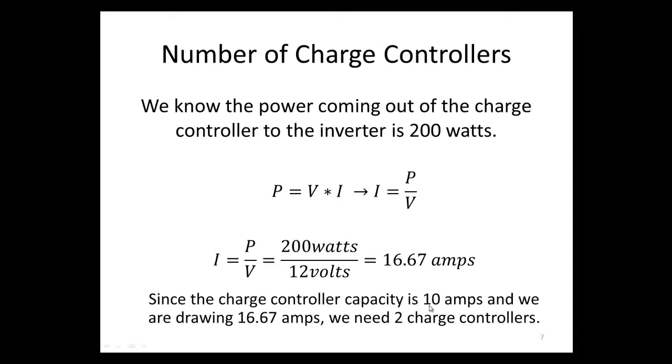Since our rating is 10 amps, and we're drawing 16.67, we need two charge controllers, because then our rating will be 20 amps for those two charge controllers.